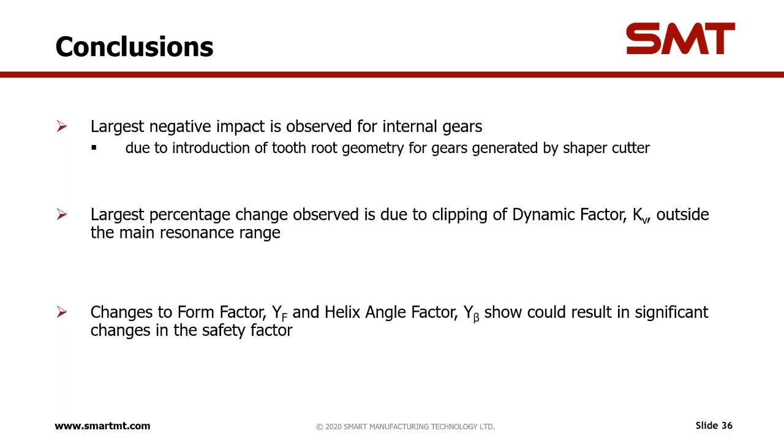So this has a rather large impact on the rating results. One thing you might want to consider is if you actually have external shaper cut gears, you can switch to using pinion type cutter and see if the root geometry would be different for those applications.